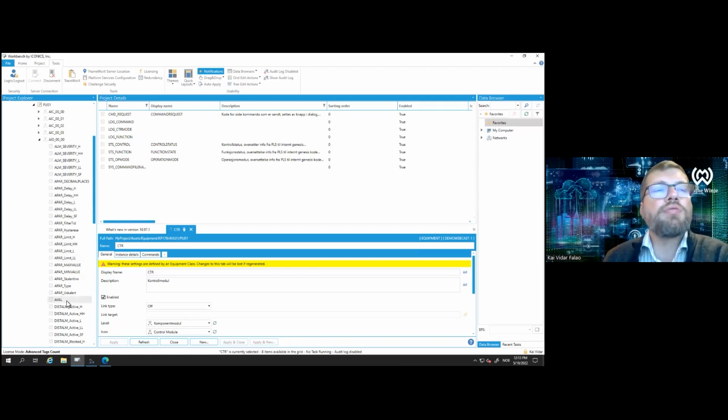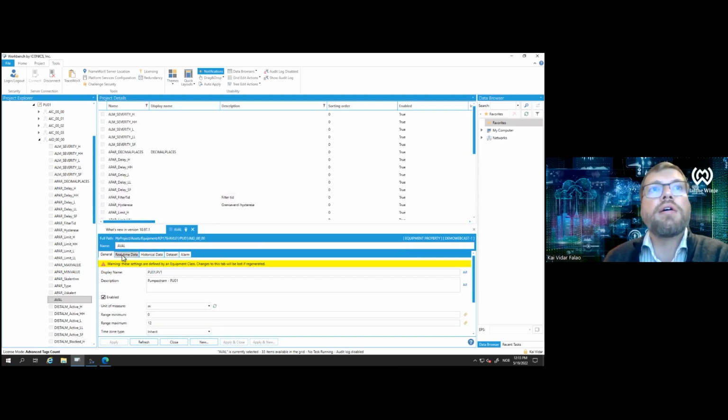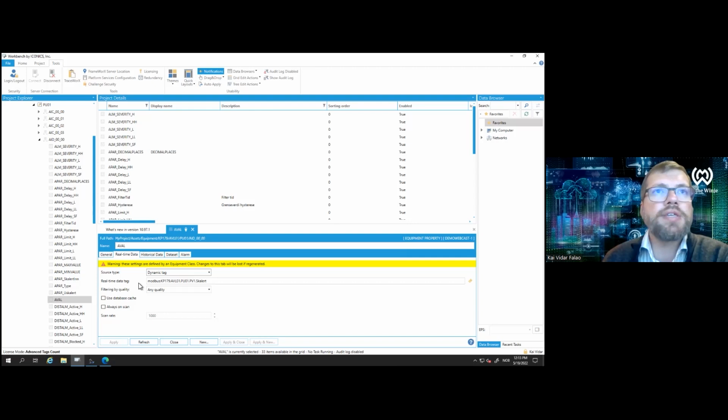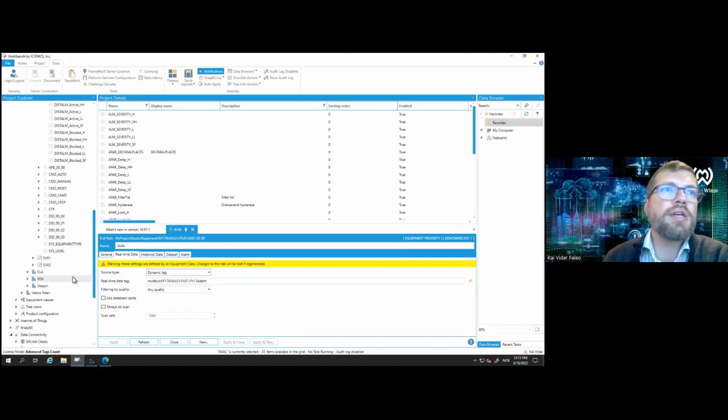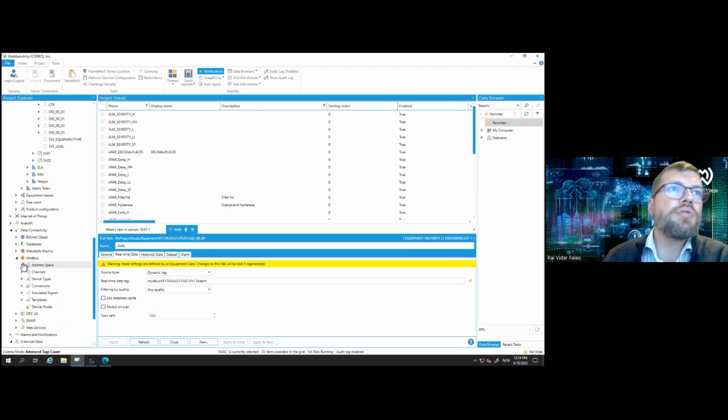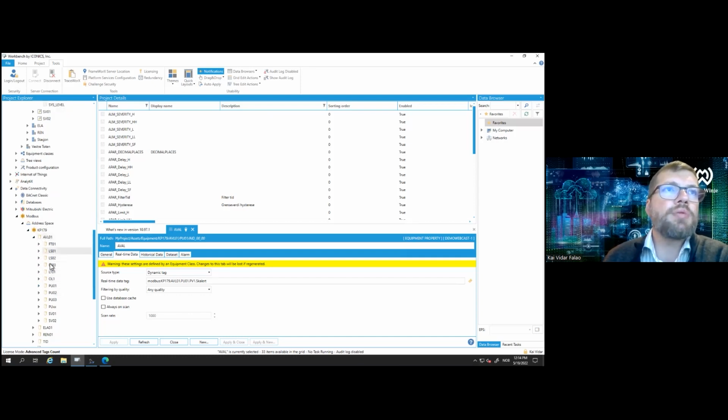In addition to being a view model for GraphWorks, for instance, it also acts as the connector box between our graphical and alarm representations, and the point managers that we use. In this case, it's Modbus. And as you can see, there's a very strict hierarchy. Again, let's call it an information model, put into this address space that we have. So it's easy for us to find each equipment, and it's laid out precisely as we like it from the engineering tool that we have.